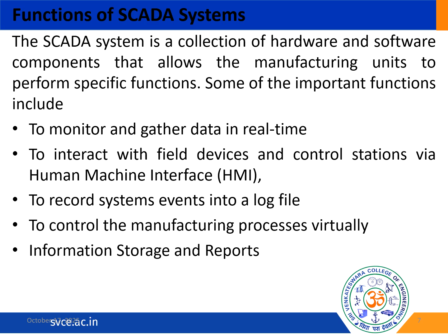And yes, we have some important functions where we can monitor and gather data in real time, and we can interact with the field devices, and we can record system events into a log file, and we can control the manufacturing process virtually, and we can do information storage and reports. So this is all about the functions of SCADA systems.